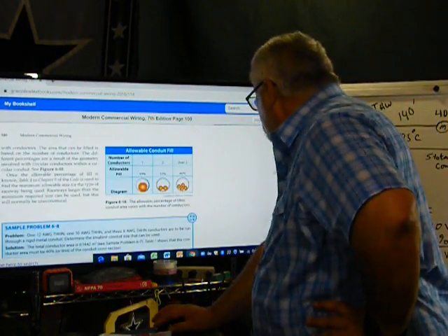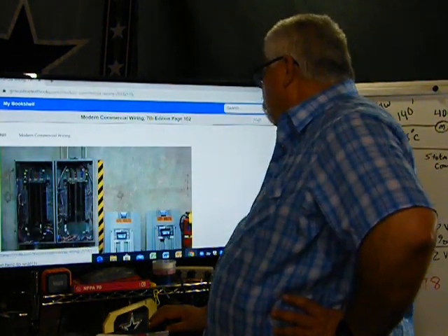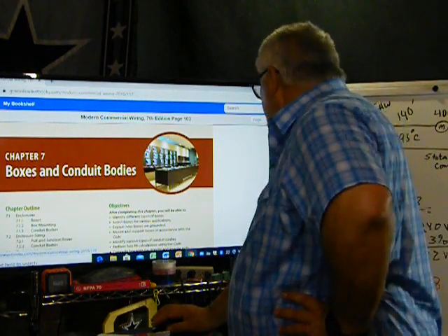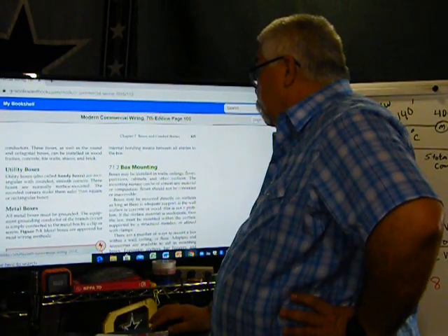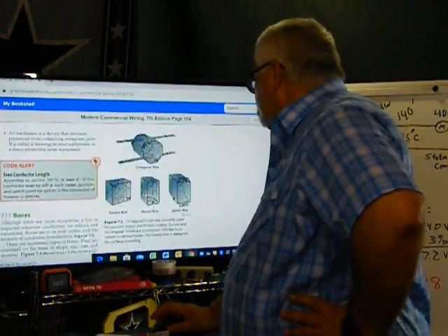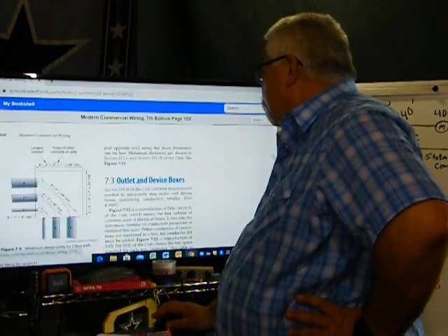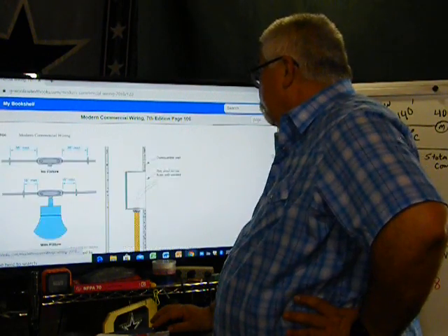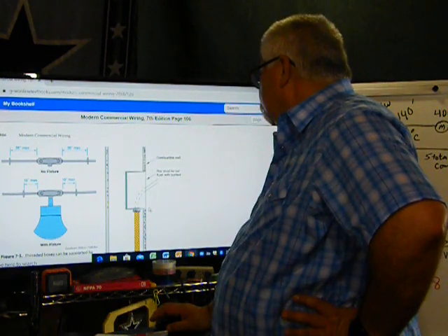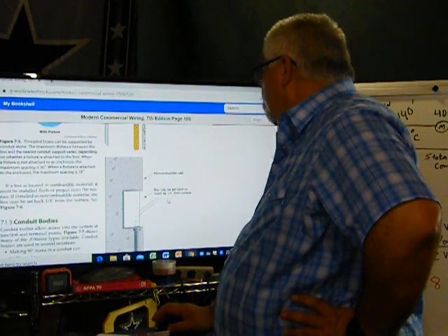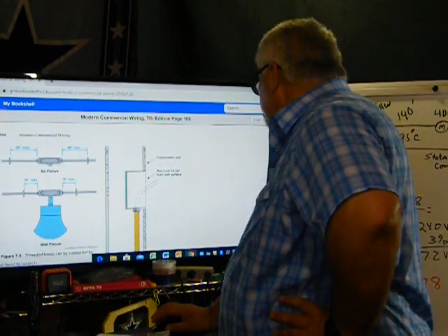Okay, well, that's one. Is conduit sizing. Table 4, Table 5. You have tables of that. The other is box sizing. Once we size it, let me go back. Okay, always remember, it's got to be flush with the wall. So if you got a combustible wall, your distances, non-combustible wall, 1/4 inch, combustible wall, flush.